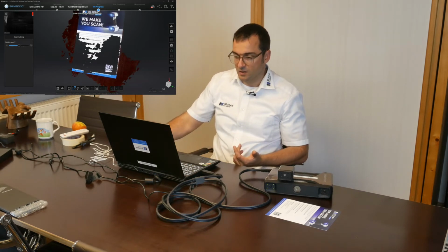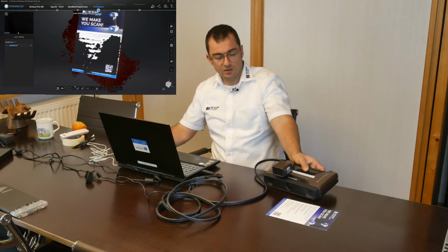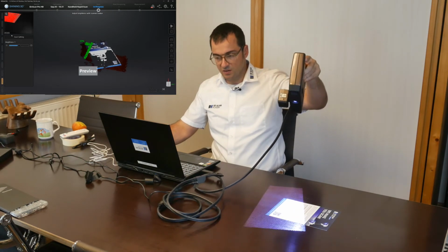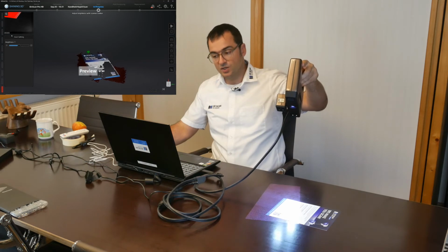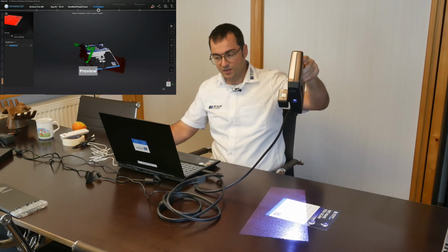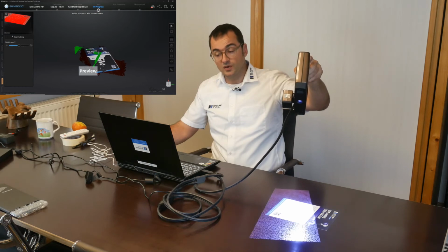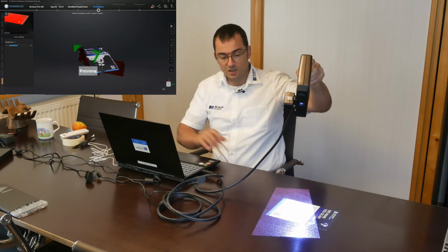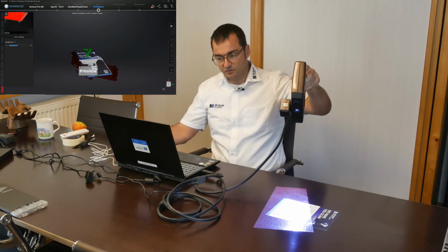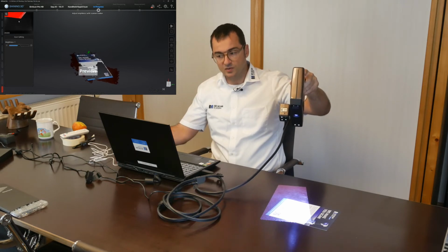Why? If you go back in that video, you can as well go in the preview, you will see we have a very big difference regarding the surface reflection of the emitted light from the scanner, the white light that you can see with that structure in it. And there is a problem about the surfaces. The white surface, that's my flyer here, is reflecting a lot of light. And the dark surface is just absorbing most of it.